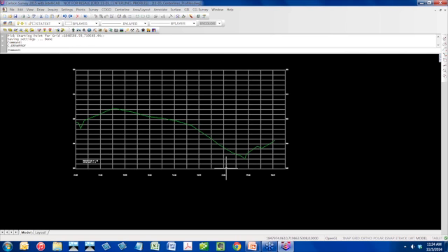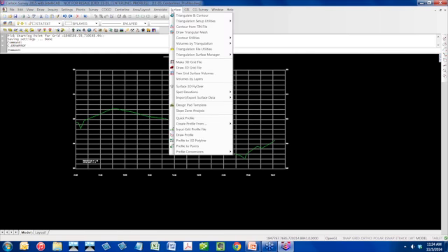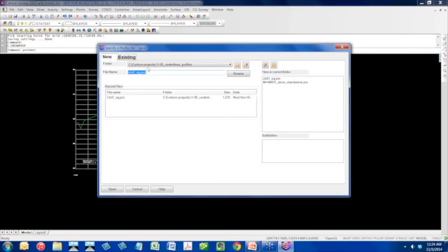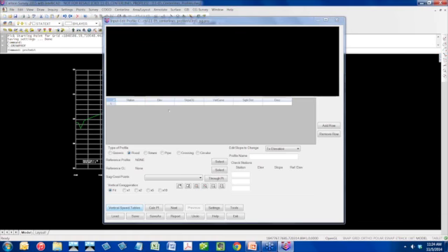So what you need to do is just go from those paper plans and plug in the profile data, like the station, the elevation, vertical curves, and so on and so forth. So just to input the profile data, we're just going to do a little road in here. I'm going to go back to the same command, input, edit, profile file. So this is the same place I was if I wanted to go in and look at a profile that I've already created, but I'm going to create a new one. So this will be centerline of road 1, PG. So this will be my proposed ground. It's a new one. Click open.